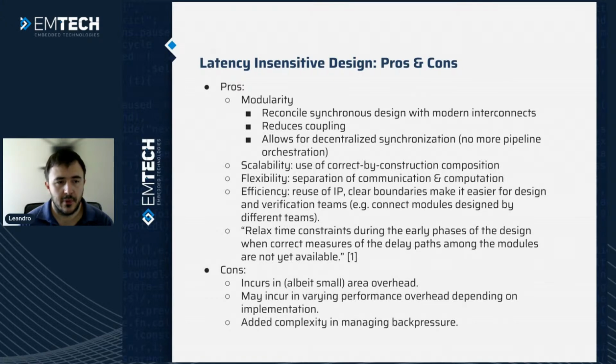If you have a well-defined set of rules, such as using a standardized interface, you should be able to hook up designs that follow the same protocol together, and they will work because of this correct by construction composition. Because the designs are latency insensitive, you can add pipelines, and the synchronization will not be lost.